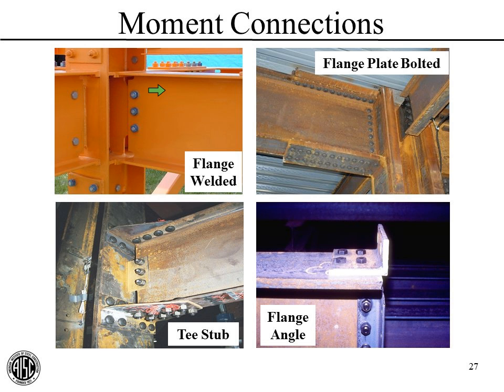So if we have a negative moment into this beam, that would turn into a flange force up here pulling this way, and a flange force down here pushing this way. Those forces would go through the stiffeners into the column flanges using fillet welds or penetration welds, and that would transfer the load effectively into weak axis bending in the column.